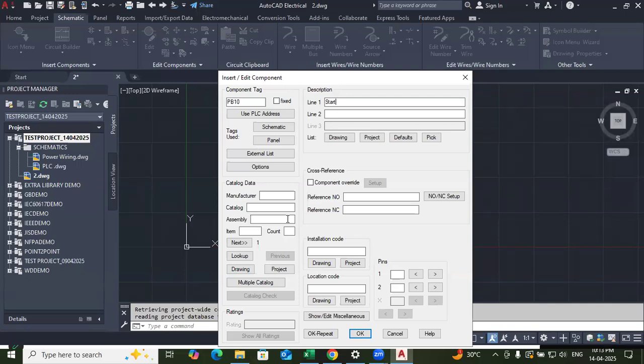When we ask for the MCB, the electrical shop person will ask a repeat question: what is the rating of the circuit breaker, what make of circuit breaker we need, like Eaton make, Allen Bradley make, or the rating of that circuit breaker like 1 ampere, 2 ampere, 10 ampere. This information comes under the catalog data, and we need to mention here the manufacturer and catalog number.